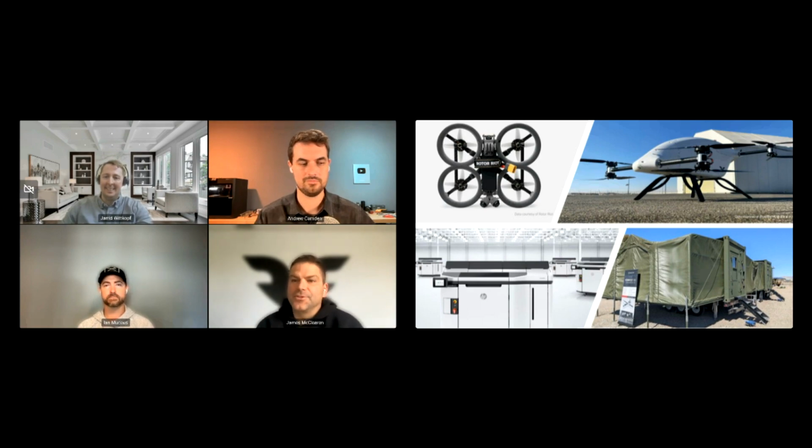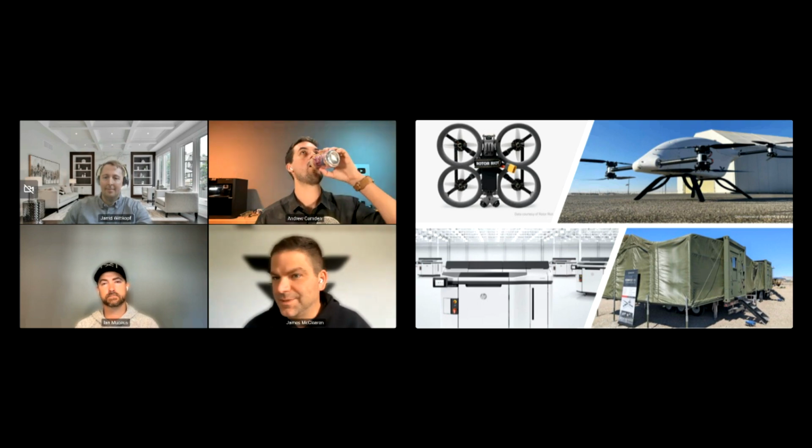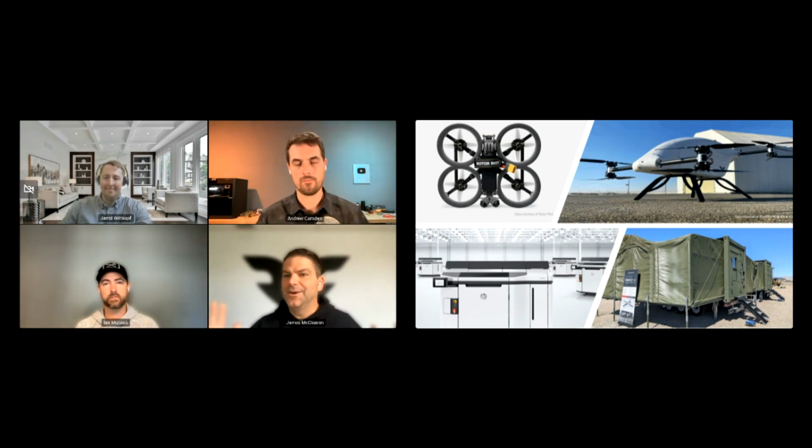Yeah, for sure. Control and traceability and repeatability is super important. But I think the other thing, we've been so focused on end parts, like we're making parts that are going on an aircraft, for example. But also the timeline of FDM, maybe MJF, and then soft tooling, hard tooling, et cetera. Actually, we make tools with MJF, right? You can make all of your soft tools and do it very fast, where you're not machining it out of aluminum or any sort of metals. So something we really didn't touch on is I think it changes the whole time horizon as well.